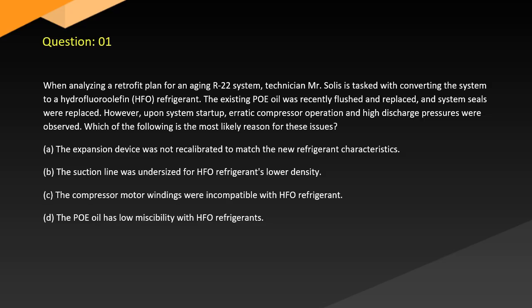Question 1. When analyzing a retrofit plan for an aging R22 system, technician Mr. Solis is tasked with converting the system to a hydrofluoroolefin HFO refrigerant. The existing POE was recently flushed and replaced, and system seals were replaced. However, upon system startup, erratic compressor operation and high discharge pressures were observed. Which of the following is the most likely reason for these issues?